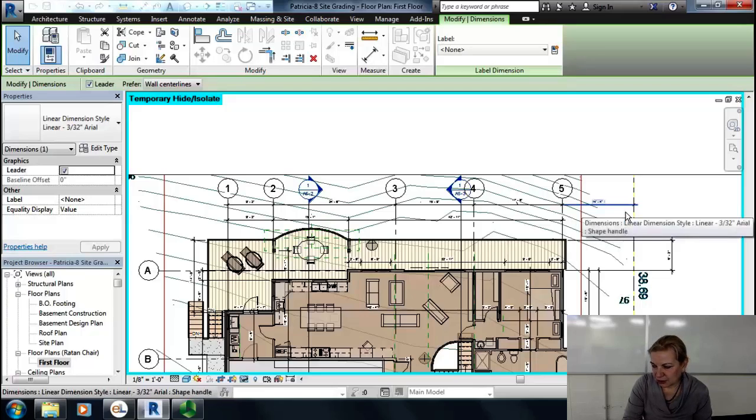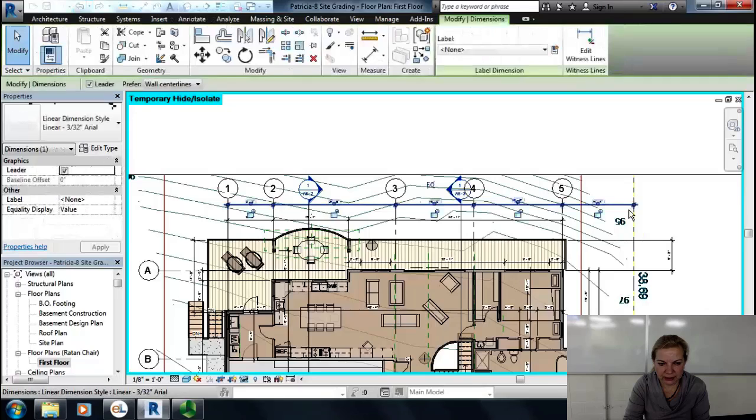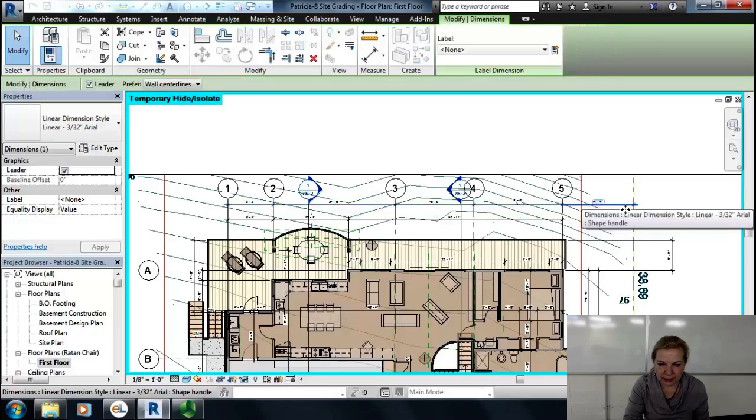For removing a dimension line, let's do it again. Will it work? It worked. So let's do it again. Undo, because it's a little bit tricky. Select the line, put your mouse close to where you want to be. Tab, Revit knows where you have your mouse and it takes you there. Click on this one. You can only remove this dimension from the string if you see on the screen only that string. And the way to do it is to tab until it's selected thicker and then click on it. That's what I just did.